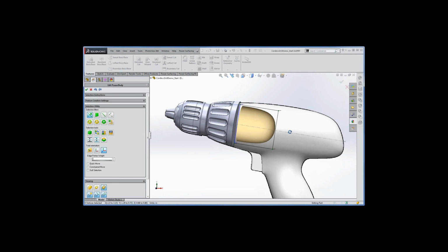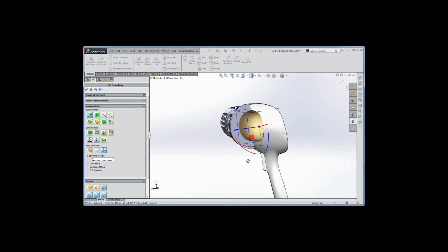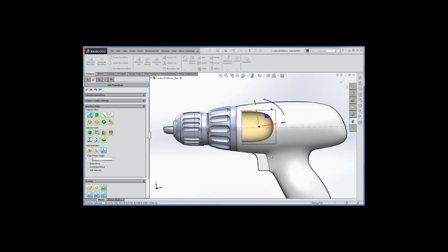And the next thing we want to do is, if we're going to aim for this edge here, we want to make sure that these vertices are fairly close to it. So I'm going to select everything and scale it down. They're not perfect, but they're close enough. The main thing we want to make sure of is that there's no ambiguity. If I push this thing all the way through here, it wouldn't know whether it was going to constrain to this edge of that ring or this edge. So we want to help it out and get it fairly close, but it's not crucial.